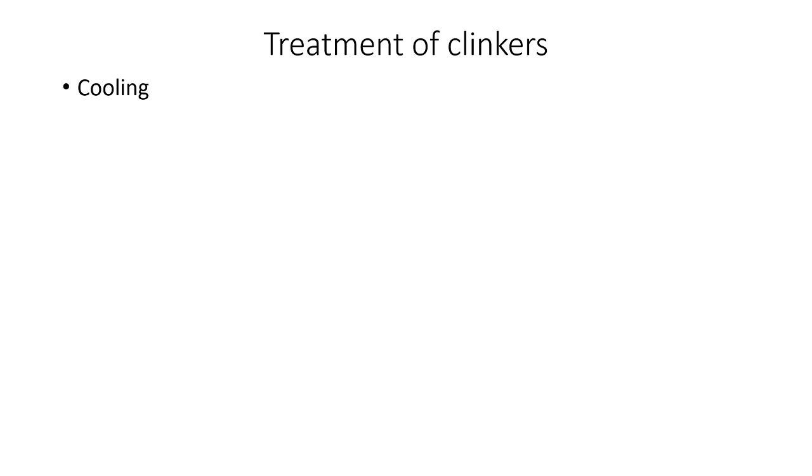Okay, means they lift in while rotating and again drop. So during that lifting and dropping, clinker gets cooled. So heat loss from the clinker is recovered and used for many purposes in the manufacture. So the rate of cooling is controlled to avoid complete crystallization of the clinker.